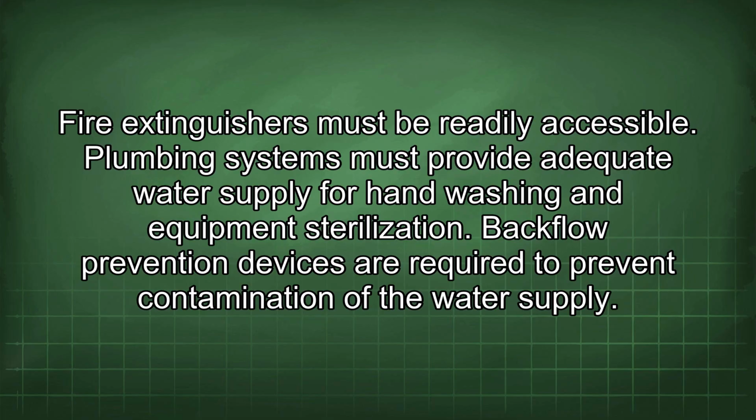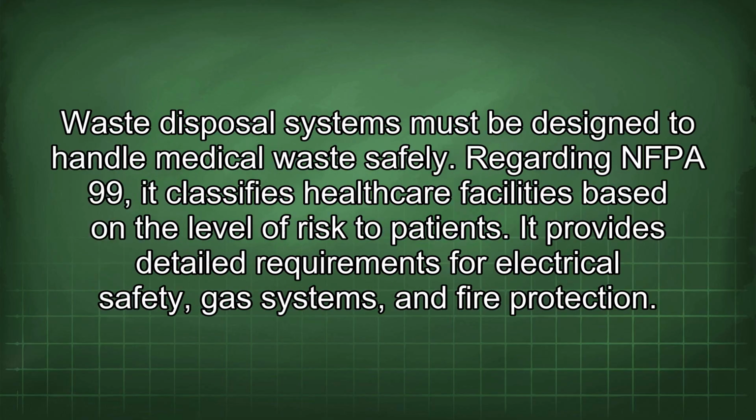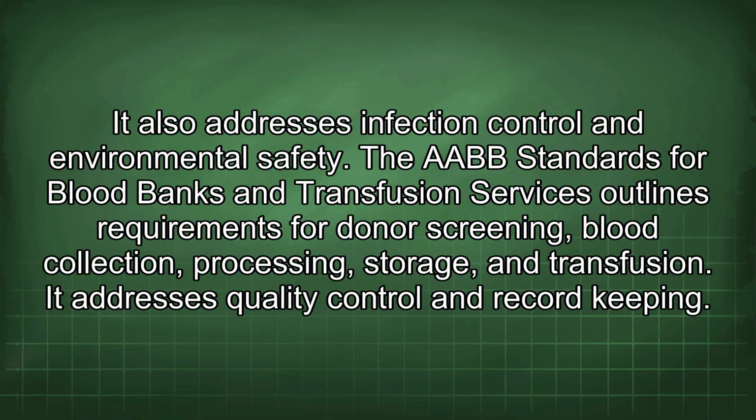Plumbing systems must provide adequate water supply for hand washing and equipment sterilization. Backflow prevention devices are required to prevent contamination of the water supply. Waste disposal systems must be designed to handle medical waste safely. Regarding NFPA 99, it classifies healthcare facilities based on the level of risk to patients. It provides detailed requirements for electrical safety, gas systems, and fire protection. It also addresses infection control and environmental safety.